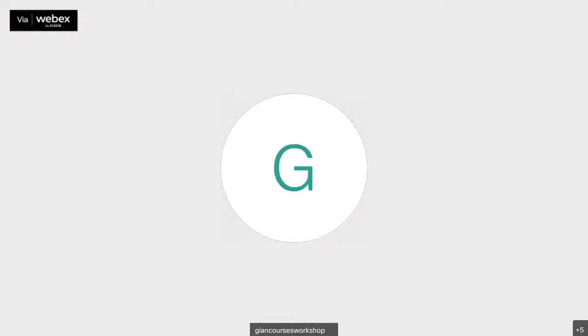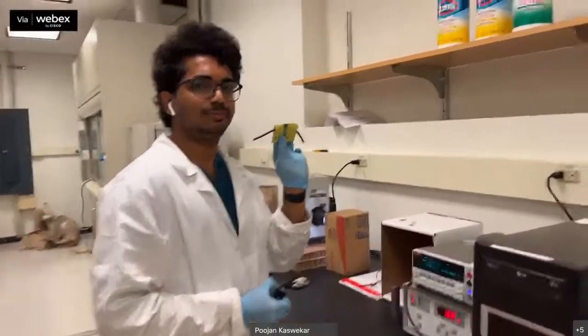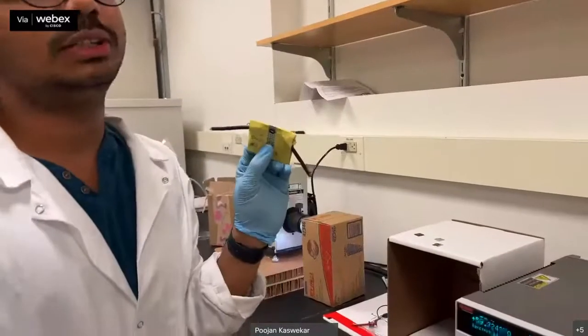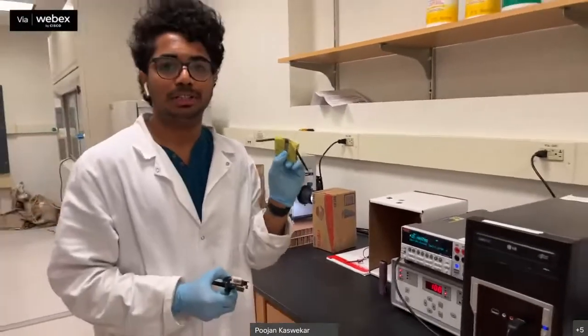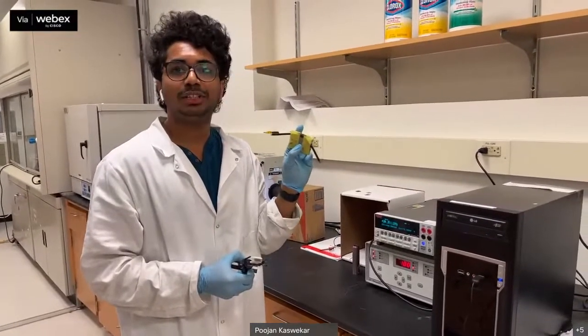Please ask your question. To measure the intensity of light, is it an inbuilt power meter, or do you have to measure with any other external power meter? No, it's inbuilt. We can measure the intensity of the light with this. They have a standard solar cell, basically. Once you know the current of the standard solar cell, suppose NREL already measured this one for me, that is 1.64 milliamps. That's what we initially measured, right?